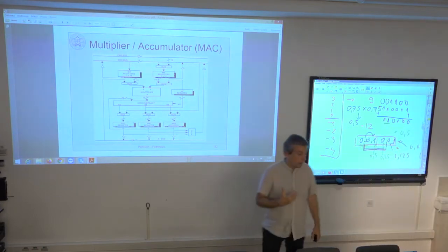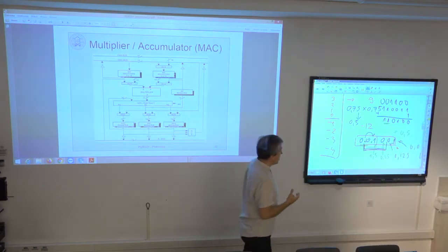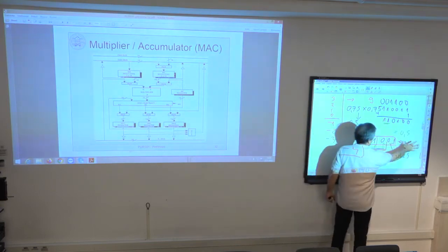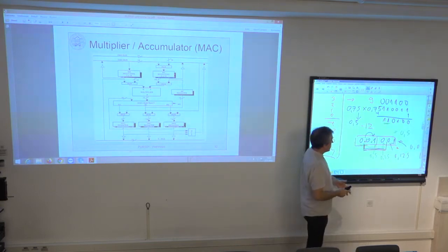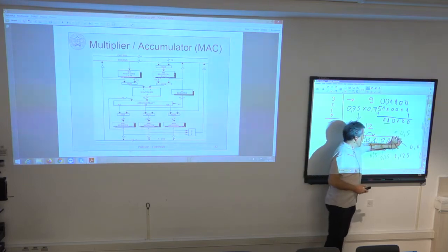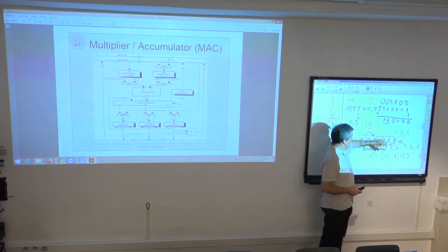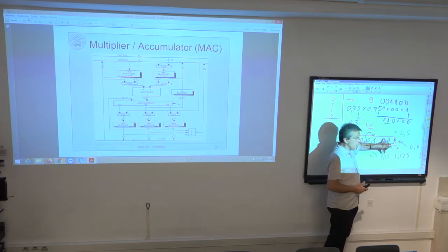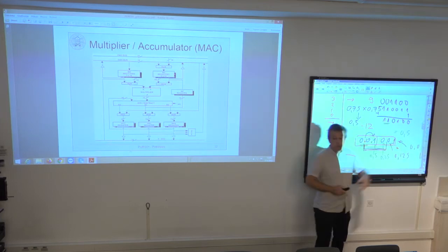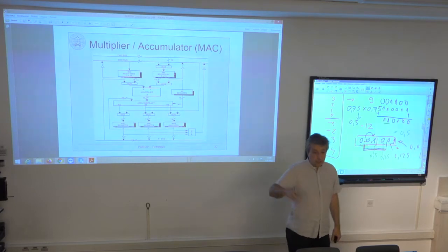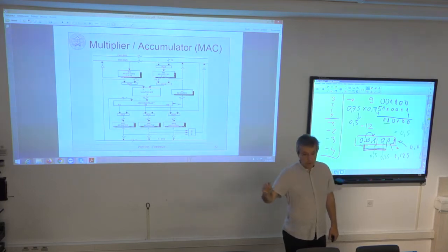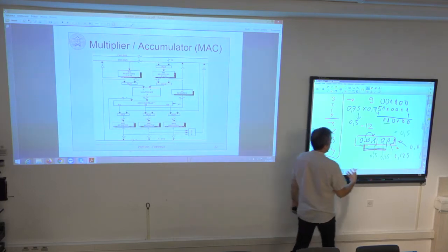And the largest magnitude of this error is whatever is thrown away. And what is thrown away is practically the same value as the least significant bit. So this least significant bit, LSB, of the upper word has almost the same weight as if all the lower bits are set to 1. So 1, 1, 1, 1 is only a little bit smaller than the value 1, 0, 0, 0. Okay, so that is the largest error that I make.